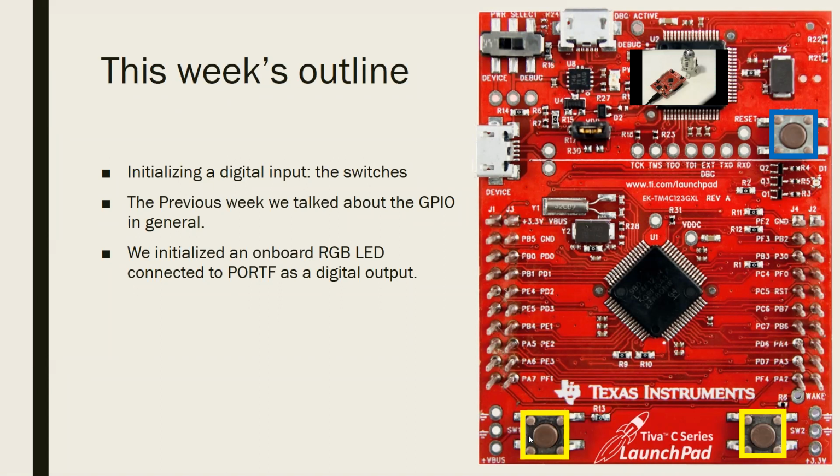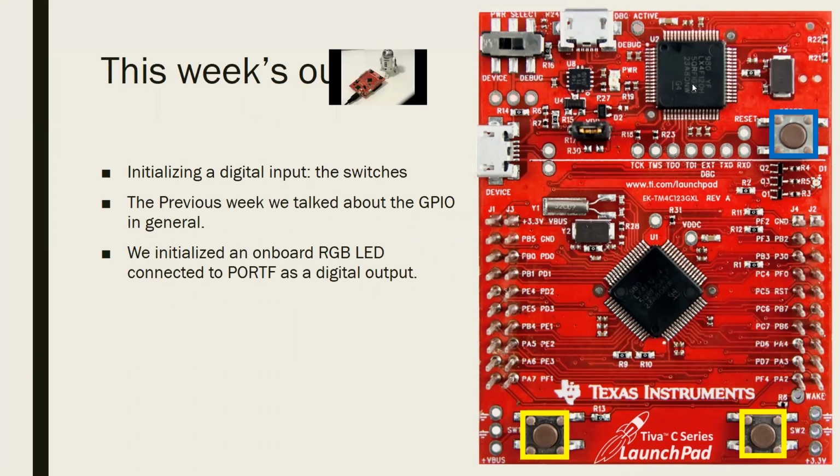If you look very closely, you will realize that there's a cable going on like this, if you can follow my mouse cursor, and it's being connected to PF4 here. This pin is PF4, this pin is PA2. And this one is connected to PF4, this one is connected to PF0. And this switch is not connected to this part of the card. It is connected to this microprocessor here, because this microprocessor is the one that controls this. It is used for resetting. So if you have code running and you press the reset, the code will restart again.